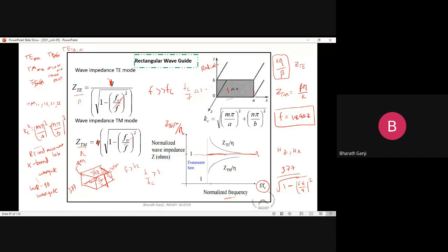Maybe it's not part of our course, but one thing I can say is, if you want to transport the energy to the outside world, you need to make an impedance match. To do that impedance match, something has to be done, because some power will be reflected back here. So if you are trying to operate close to the cutoff frequency, for example the waveguide we had earlier, the cutoff frequency was 6.6 gigahertz. Say for example I want to use this waveguide to radiate energy at 7 gigahertz. That is a stupid idea.